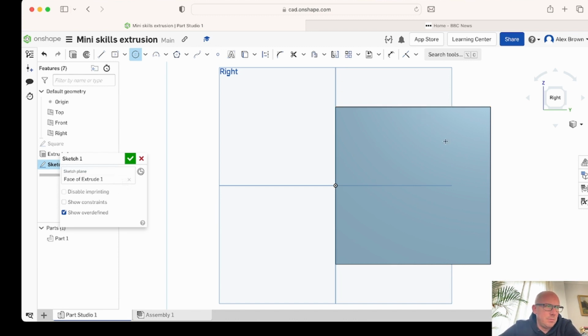But also, if I go over here, it happens again. As long as I've hovered over both of these, if I go to one of them and drag down, you see that? Hopefully you can see that little yellow line. That's a construction line. I'm not clicking, I'm just being careful, and then it'll pick up. There you go. It'll automatically pick up the other point I previously hovered over. That now I know, because that's all lit up, I know that's the centre.